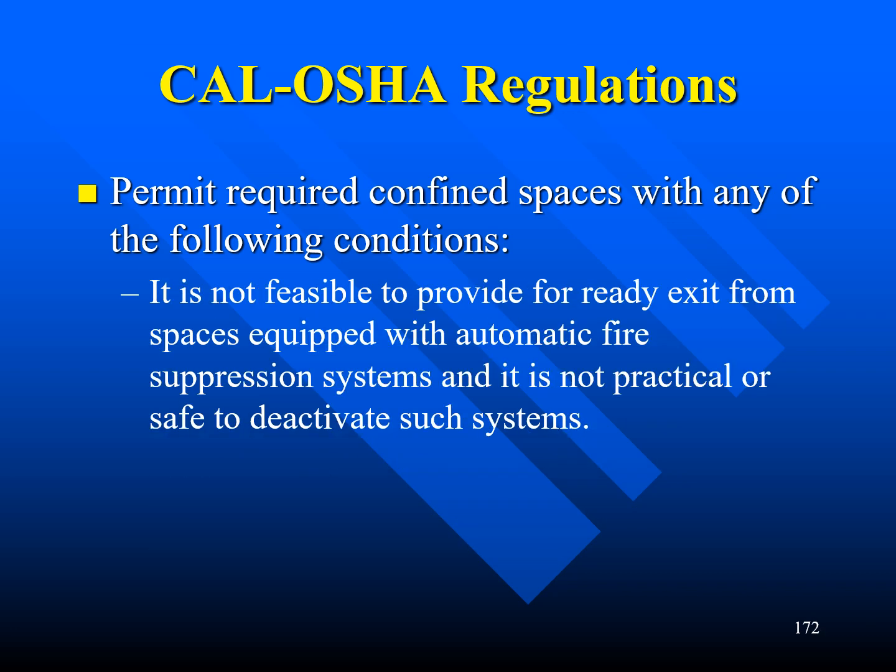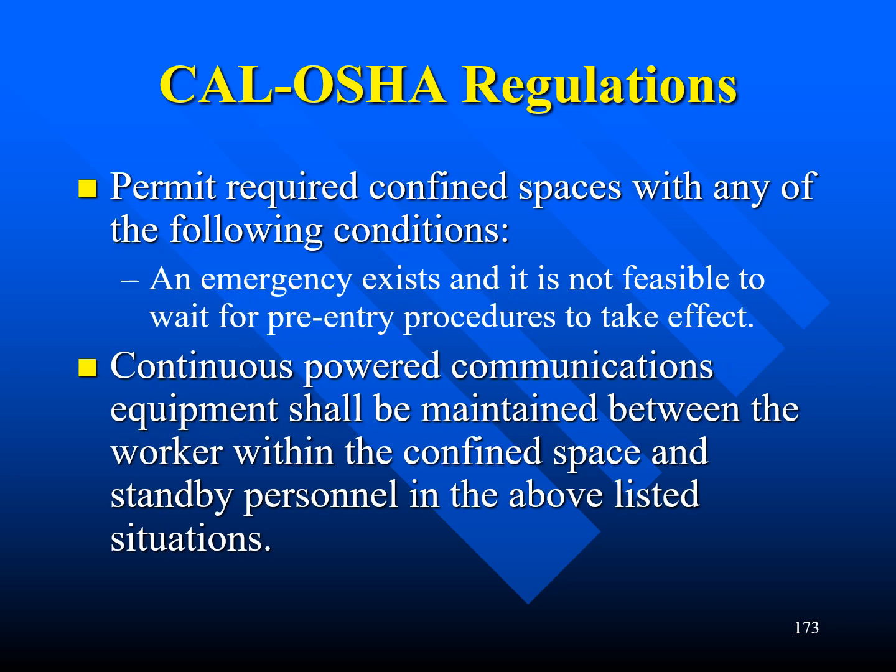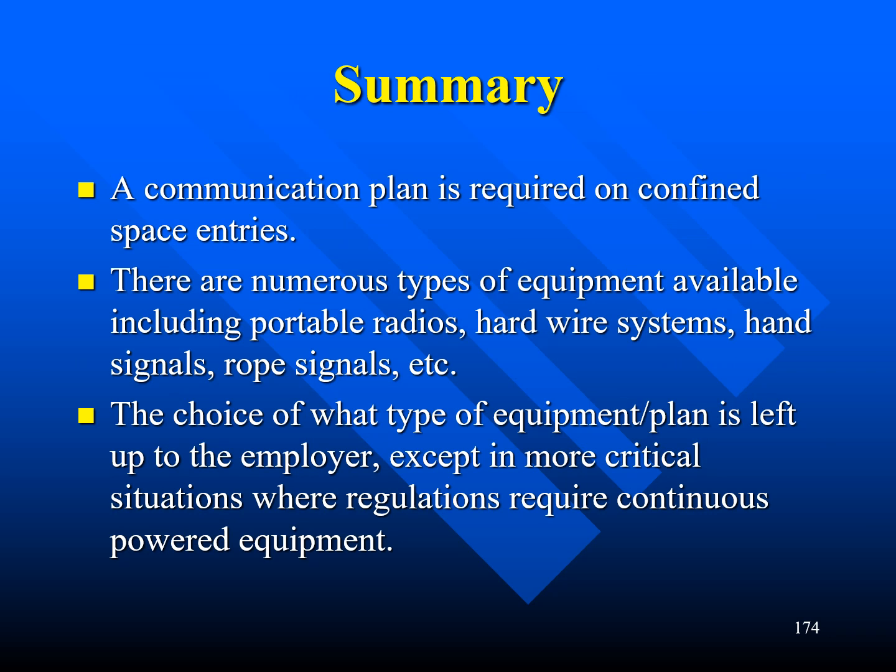Or it is not feasible to provide for ready exit from spaces equipped with automatic fire suppression systems, and it is not practical or safe to deactivate such systems. Or an emergency exists and it is not feasible to wait for pre-entry procedures to take effect. Continuous powered communications equipment shall be maintained between the worker within the confined space and standby personnel in the above listed situations.